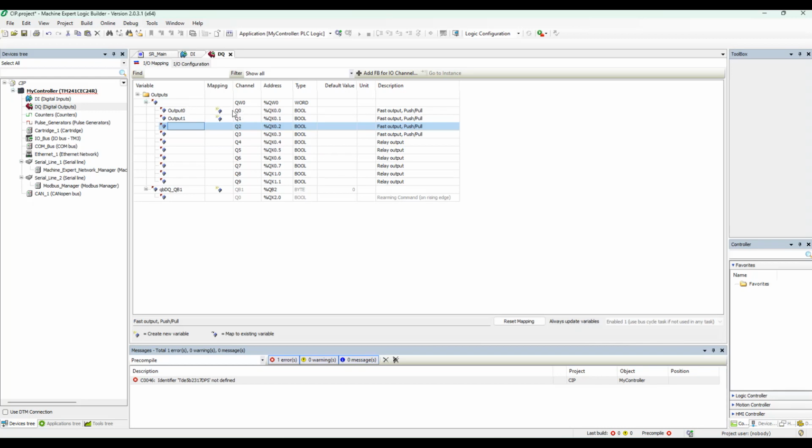So you could also, again, with the inputs, you can address them with this value right here, or you could use the declaration. I find personally it's easier to use the declaration, and easier for anyone following your program to use the declarations rather than the actual address itself, because in my experience, if you use the address itself, now you have to get the schematic if you have it, and you're going to have to follow through the program looking at the schematic, and it just makes it a little more difficult. So I would highly recommend making declarations that reference whatever field device your inputs or outputs are actually going to be controlled by or controlling.